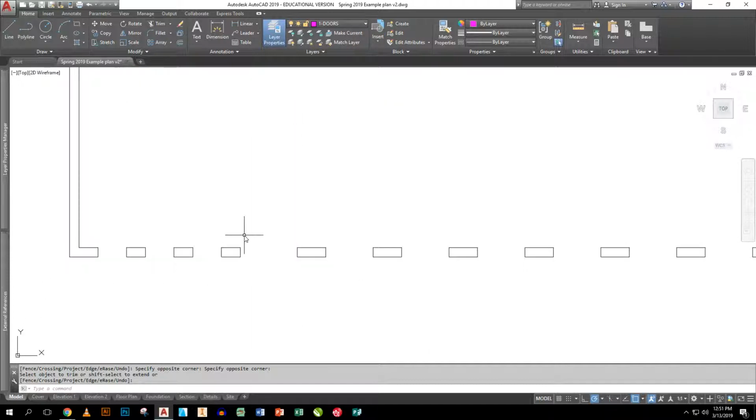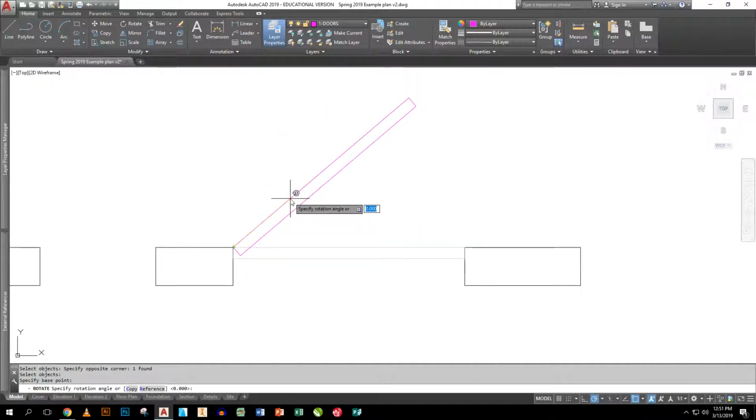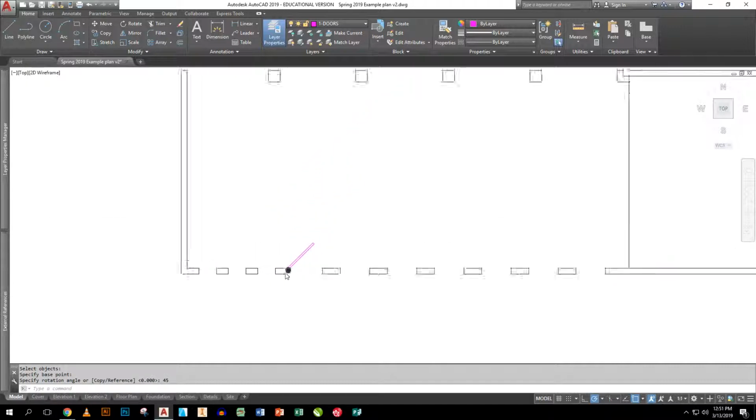Well, this door right here, if I just draw it as a rectangle, REC, from right here where the hinge is going to be, and I'm just going to drag it out this way, and I tell it to go at 36, minus 1.75. That's actually going to make me the right size of a door. So doors are actually about 1.5 to 1 3/4 inch thick typically. Now if I just rotate this around its pivot point right here, in other words where the hinges would be, I'm going to tell that to go 45 degrees. There's my door symbol right there for a regular swinging door.